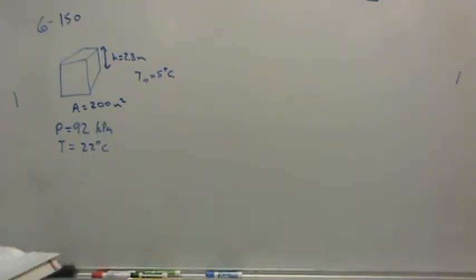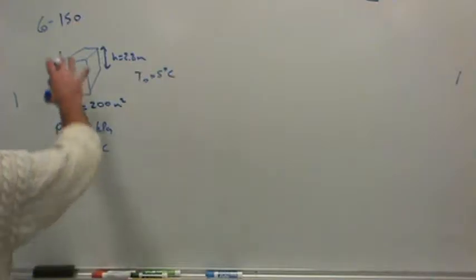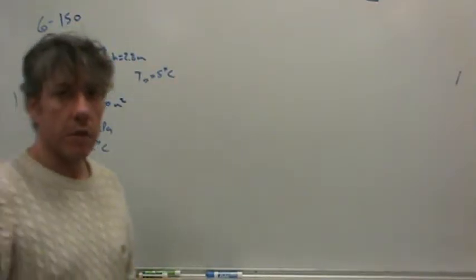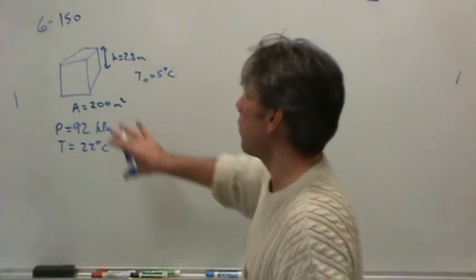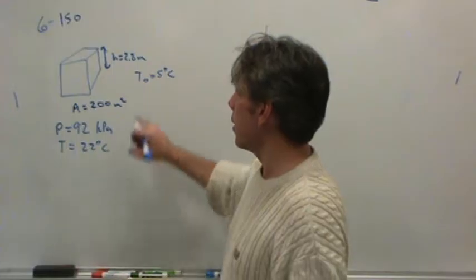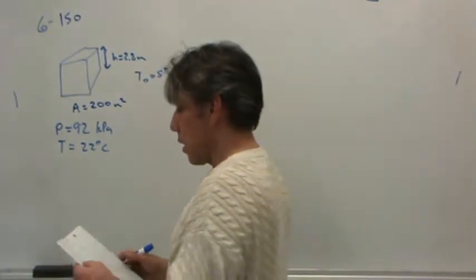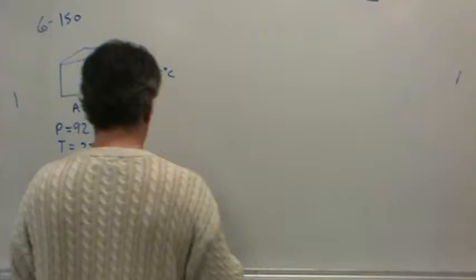There it is. Okay? So let's figure out how much it costs to leave a vent fan on for an hour. Now, one of the things that we have to note is that it says the fan can discharge a house full of air in 1 hour. So that 1 hour that the fan is on, all the air in the house is going to be exchanged. In other words, say it's wintertime, we're going to pull in the cold 5-degree air, have to heat up all the mass of that air to 22 degrees Celsius.